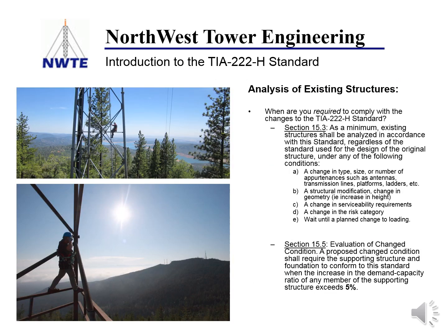Okay, analysis of existing structures. Obviously very interesting to figure out when we are going to start running this H standard, or when it is required. But in general, if you change the type, size, or number of appurtenances on your tower, you will be required to run the H standard. That really is the big one.